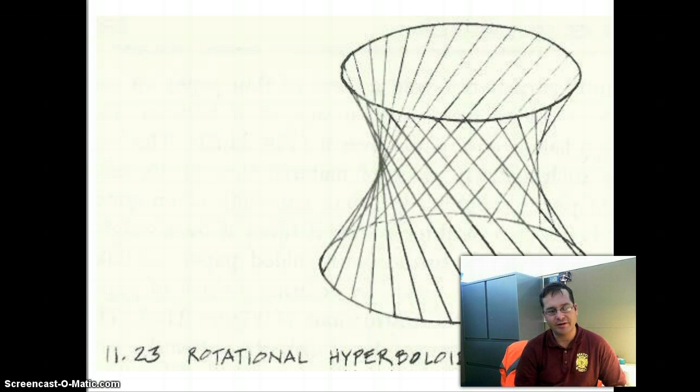And in this cooling tower, they're essentially pumping water to the top and allowing it to cascade to the bottom, and in the process evaporate. And those towers develop a convection current of air coming through, and it turns out that this hyperboloid shape is useful in assisting that airflow. Again, not real common to building construction, but it does illustrate the use of complex curves to generate a surface.